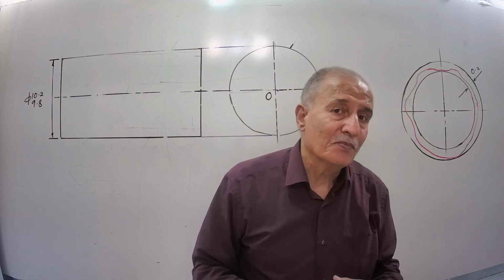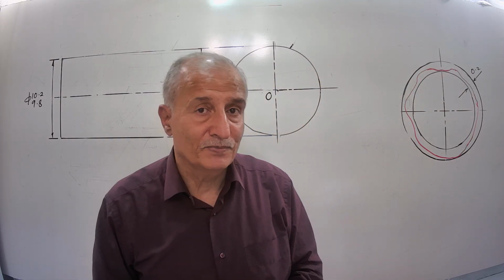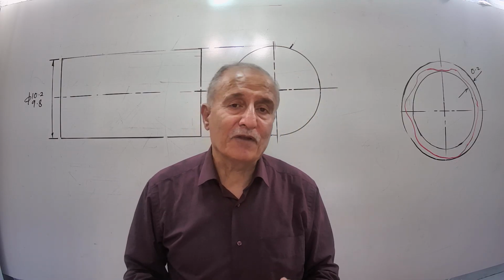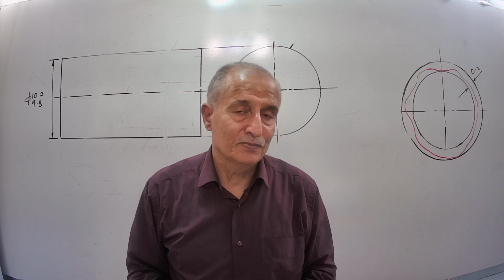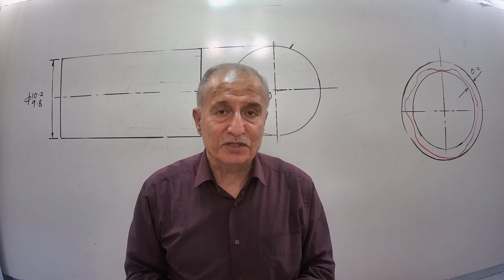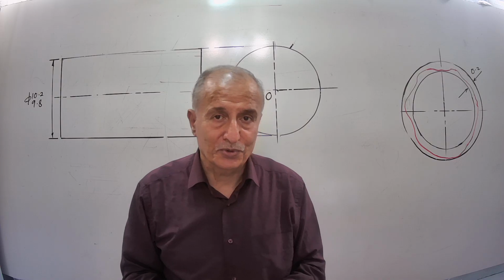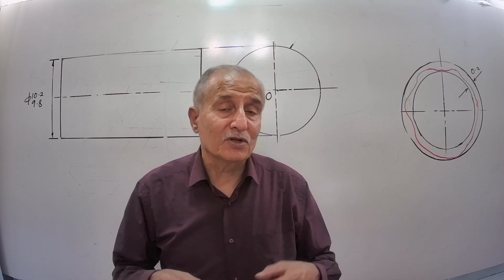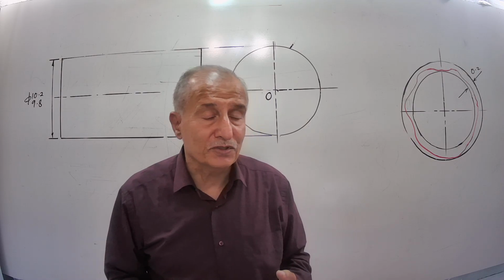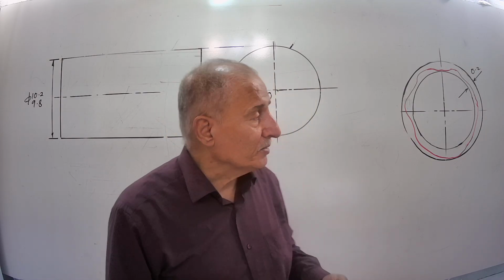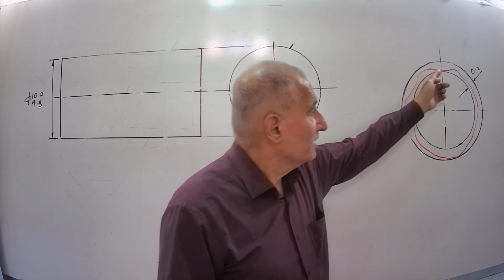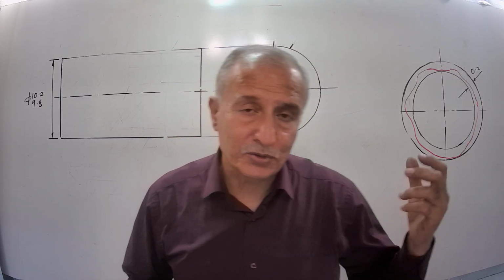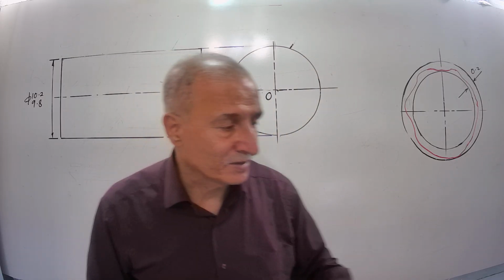How much you deviate from a perfect circle is decided by the designer. Don't go more than, for example, 0.2 error. Otherwise, the part will be rejected. This is called circularity error: a circular cross section must lie inside a zone, which we call the zone space, and the size of that is determined, for example, 0.2, by the geometric tolerance.